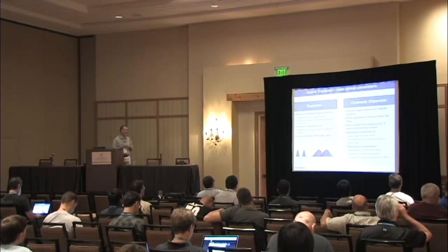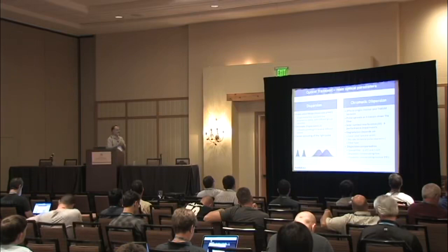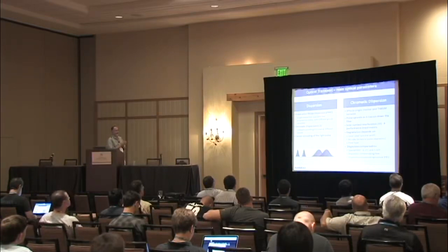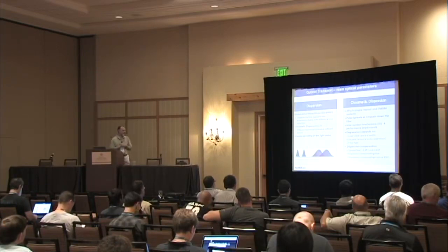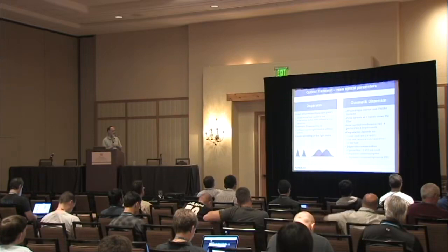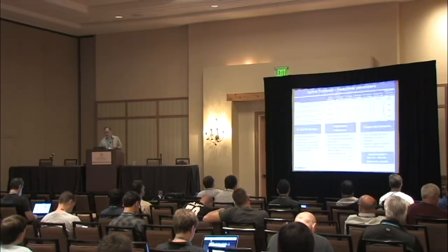How do you compensate, mainly for the chromatic dispersion? As I mentioned, special fiber, you have those two types of fiber. One is zero dispersion, the other one is low dispersion. That can help manage this dispersion. And then you can have dispersion compensating fiber. You put a small spool of fiber that causes the signal to go back to the nice shape. The same compensation is done by a dispersion compensating module that has fiber grating inside.